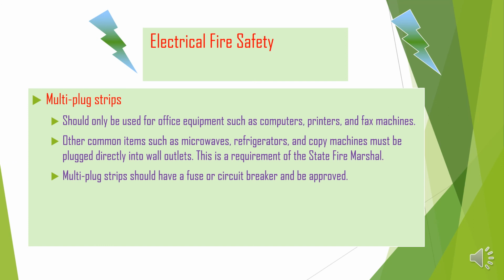Should only be used for office work: computer, printer, machines. Don't use it for other things, like machines inside the lab, inside the pharmacy, inside the ICU, inside the engine room. No, don't use it. Multi-plug strips should have a fuse or circuit breaker of their own, so it can stop the fire when something is going on.